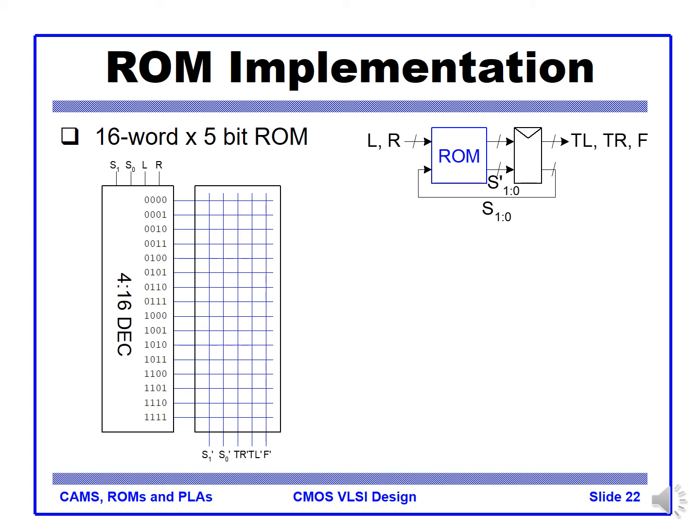Once we finish the state machine, we fill in the state machine contents. We have a 4-bit address composed of 2 bits of current state and 2 inputs from the sensors. So the 2 sensor inputs come in along with the current state, and the new state and outputs, turn left, turn right, and forward signals, will be mapped.